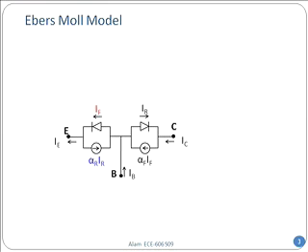And the diodes essentially face away from each other, because it is NP and then PN between emitter-base and base-collector. You can also see that there are 2 other current sources, again facing each other and opposite to the direction of the diode. So very easy to remember. One thing you will notice is that the current source for emitter-base depends on the current I sub R, the reverse current, between base and collector.